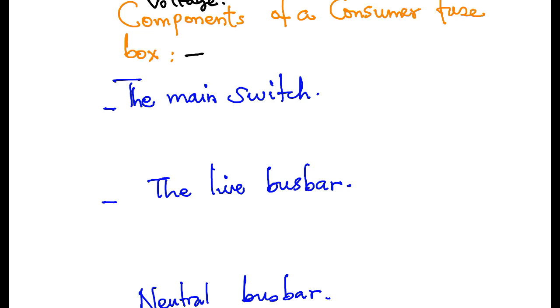One is earthed at the transformer. The earthed one is called neutral cable, and it is at zero potential, while the other one is live. The cable goes through the electrical company fuse box, where the live wire is connected to a 60 amps or higher fuse value.